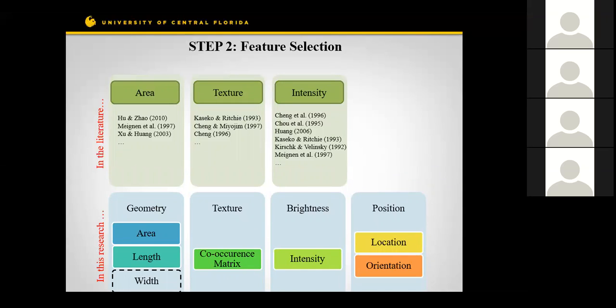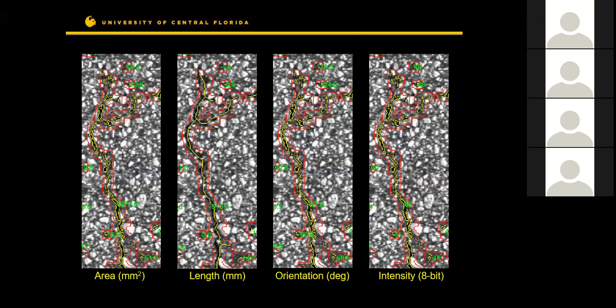And just a side note on that. One of the advantages of the image-based or computer vision-based system is that you have access to sub-millimeter accuracy images of the pavement. And if you can quantify the cracks, detect them, then you will have quantified statistics with sub-millimeter accuracy from the cracks.